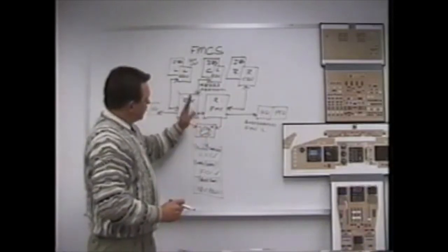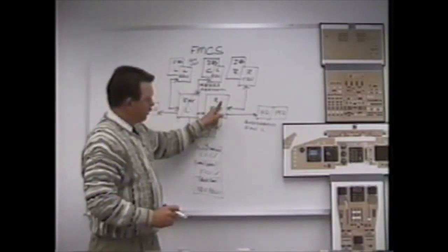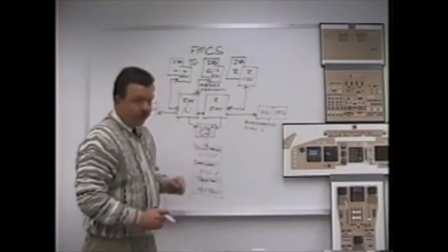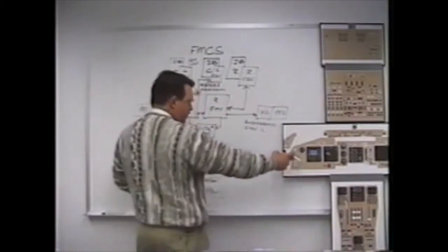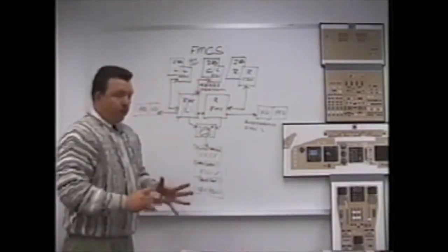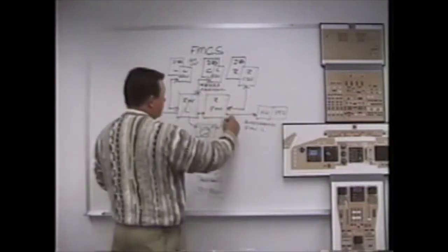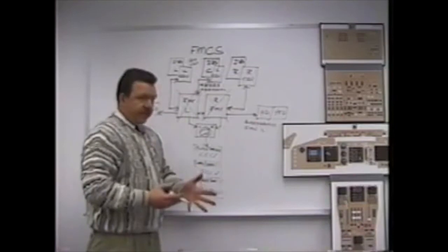Please note that if this FMC was to fail, it will not automatically switch your systems over. The irregular procedure has us doing it. Likewise, this will not automatically switch over. The irregular procedure has us moving that display switch. So then you're having a really bad day, and the right FMC fails too. If both FMCs are dead, we're in standby navigation.